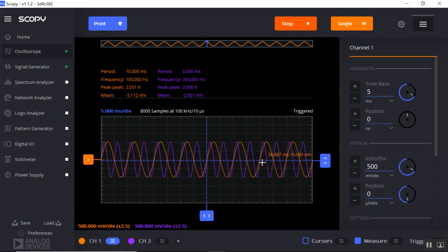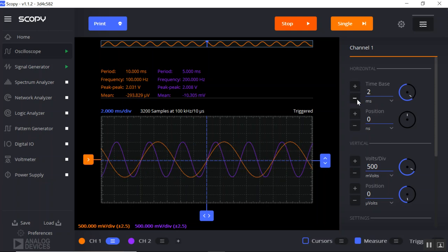Now, if you want the most accurate time measurements, you try to zoom into where you're getting about 2 periods or 3. You can leave it at that. Right. Now this is at a higher frequency, and so I can't zoom in this one, otherwise the lower frequency waveform you won't see the whole thing.